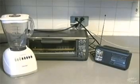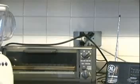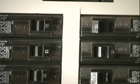You see, the more electrical appliances that are plugged into a circuit and turned on, the greater the need for a greater flow of current. The more current that is flowing, the greater the danger of overloading the circuit and causing a fire. Circuit breakers are designed to allow a certain amount of amperage to build up in a circuit. For instance, a circuit may be designed for 20 amps. That means that as long as the amperage in that circuit stays below 20, the flow of current will continue. However, if the amperage goes above 20, then the circuit breaker trips and the flow of current is stopped.